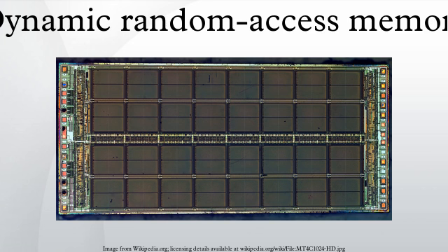Single data rate. Single data rate SDRAM is a synchronous form of DRAM. Double data rate. Double data rate SDRAM was a later development of SDRAM, used in PC memory beginning in 2000. Subsequent versions are numbered sequentially. DDR SDRAM internally performs double-width accesses at the clock rate, and uses a double data rate interface to transfer one half on each clock edge.